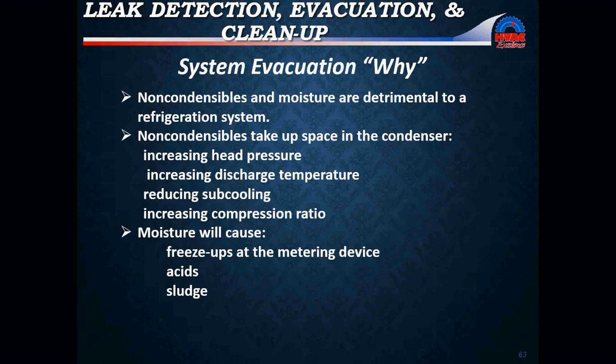But why? Why do I got to put it in a vacuum? Why do I got to evacuate a system, guys? Well, guys, non-condensables, moisture. We don't want it. They're detrimental to a refrigeration system. You're going to destroy valves. You're going to destroy compressors. You're going to have screwed up metering devices.